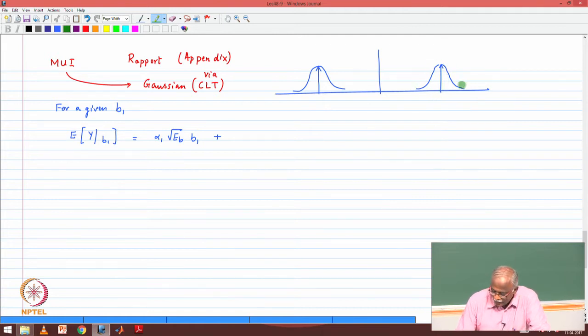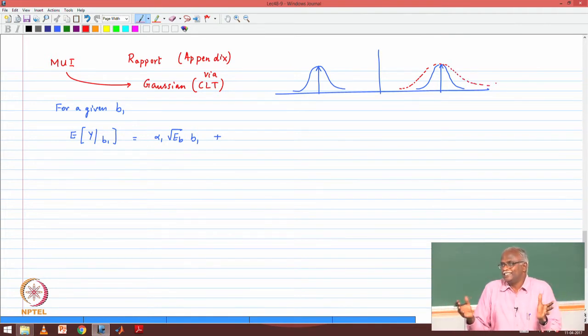There is a noise that is present because of the Gaussian noise, and because our multi-user interference also happens to look Gaussian, we are going to draw it in this fashion. It is as if you had a Gaussian noise of slightly larger variance. Basically, that is the impact, or at least a way to start to visualize the multi-user interference.